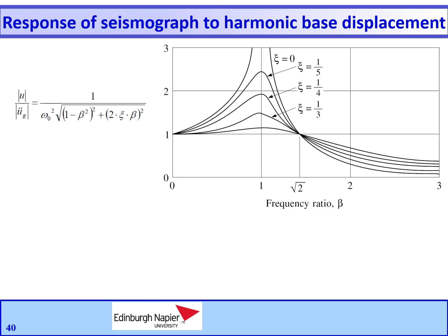The object of the instrument design is to make the dynamic response factor and the ratio of the phase angle over the forcing frequency as independent of excitation frequency as possible, because then each harmonic component of acceleration will be recorded with the same modifying factor and the same time lag.